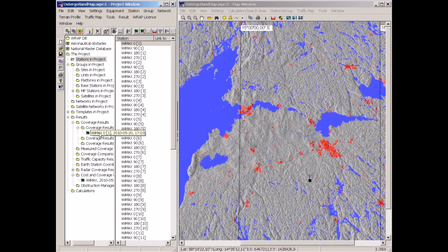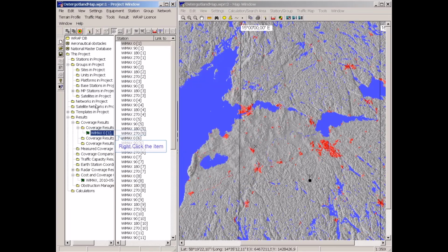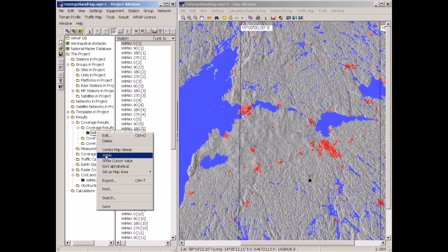So here it shows that within the 30-kilometer radius that I calculated, if we wish to have line of sight coverage to every point within that circle, we have to use a 152-meter high antenna, which of course is not realistic. So let's put in a few antennas here. What can we do with 5-meter, 15-meter, 25-meter high antennas?